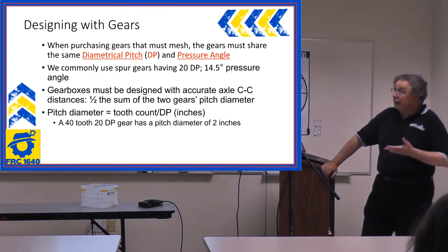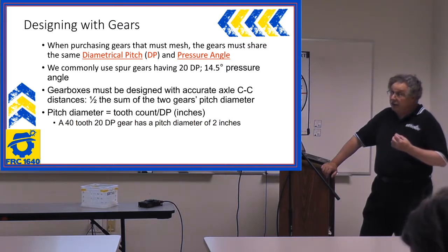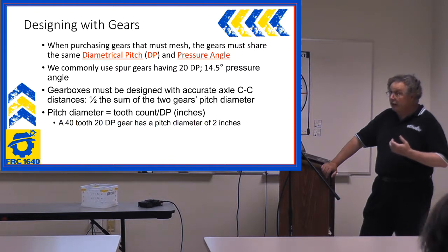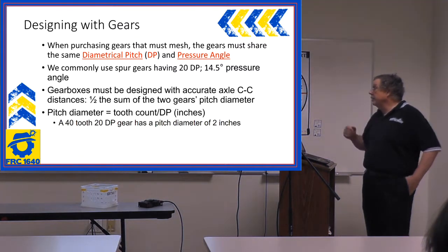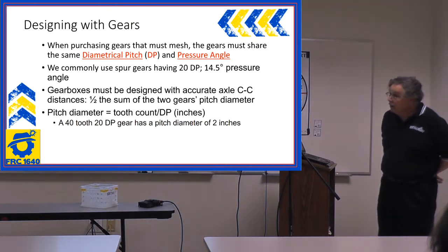If you're designing with gears, and we did this for the climbing gearbox, that was a homegrown gearbox that we put together. When purchasing gears that have to mesh, the gears need to all share the same diametrical pitch.